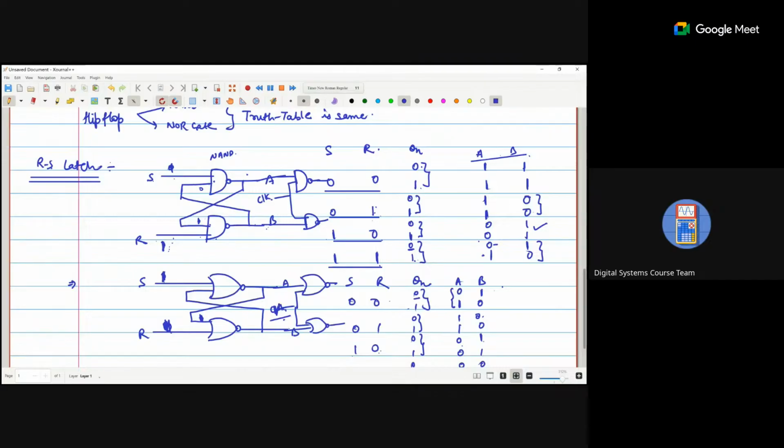So there is no particular effect of that clock pulse. So we can add one clock that is the edge triggered clock, and that will control the behavior of the output. So that is a flip flop. So we convert a latch unit into a flip flop by connecting a two-stage cascade combination.